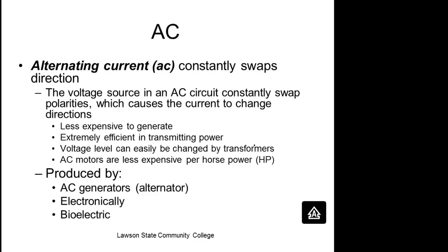Now, the most popular method is to move the magnetic field. If I had a permanent magnet, all I'd have to do is put the permanent magnet here, and then I would put coils of wire up here. Then all I have to do is have a prime mover cause it to spin, and it would make AC. Of course, I would connect these together. That makes sense?